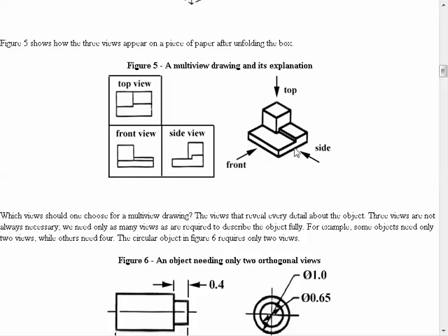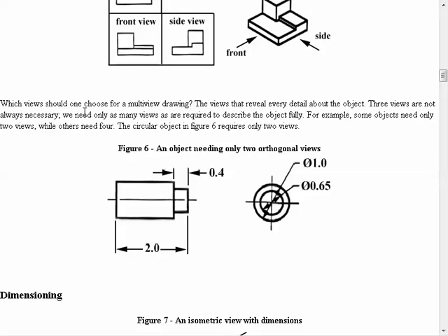Quite often an engineering drawing will have the three views and an isometric view or some other three-dimensional view on the drawing, with then an awful lot of detail added to clarify what's going on. Now, you don't always need three views of an object to fully describe it, because sometimes two of the views would end up being the same.